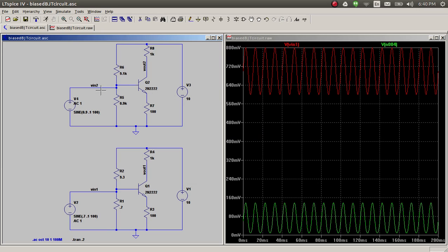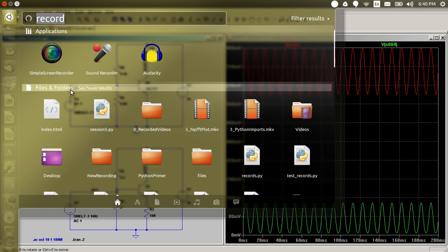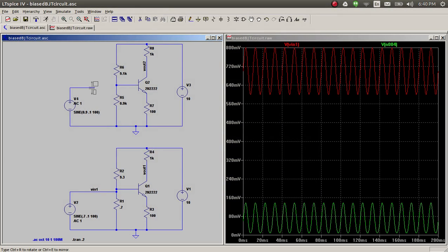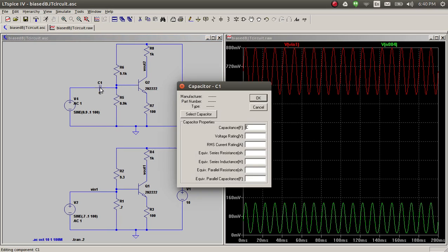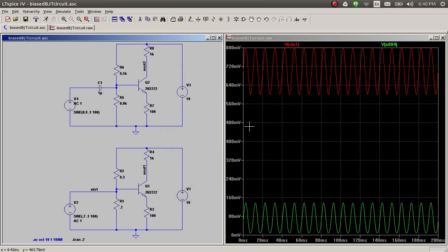kilo ohms, and I'm going to put a capacitor here. It can be any value capacitor for starters. What I'm trying to do primarily with the capacitance is disconnect the bias from here to the output. So if I just add a cap, I can rotate the capacitance and put it here. And I have to put a value, so let's say I just put a microfarad of capacitance.